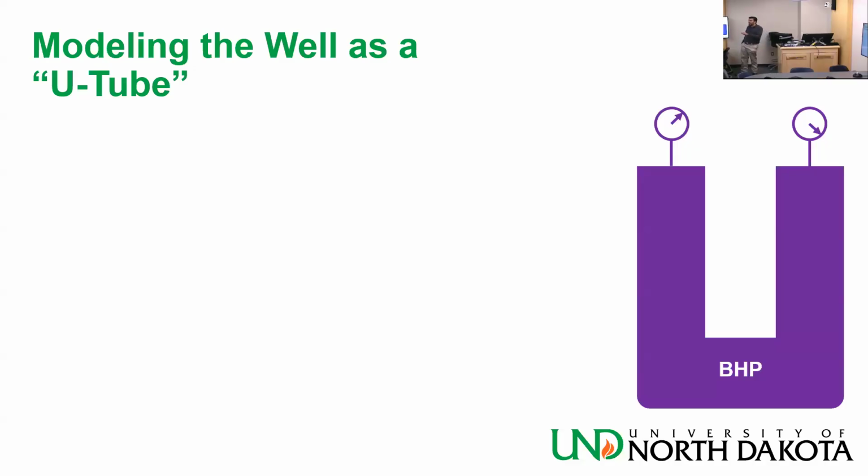And from the mud weight and the depth of the well, I can tell you the bottom hole pressure, right? We will see the equation of how to do it. Some of you already know. You need to be able to convert mud density and depth to pressure, and pressure and depth to mud density. So I give you two, you can give me the third. That's the idea. And I want you to be very, very familiar with it.